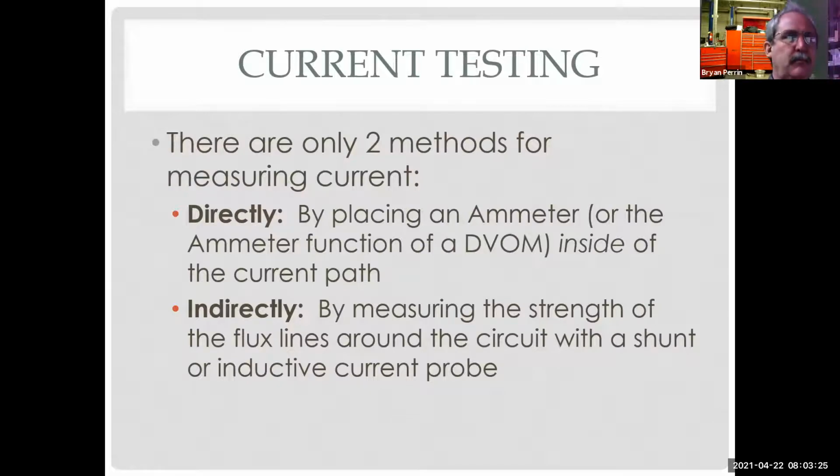And so I can also do that. I might do that in the case of ignition coils or fuel injectors, because I can see very quickly if I have one that's bad or something that's out, versus taking everything apart and testing every one. So current testing has its place.